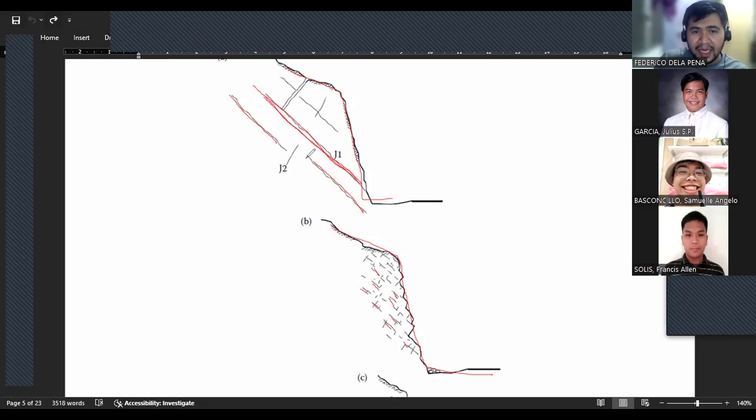Now, in terms of stability, that will have implications on how the rock slope may fail. If you have even just one discontinuity that is highly persistent, it can easily create an unstable block that can cause a large failure, like in this illustration. On the other hand, if you have low persistence joints, what they would normally form are small blocks, and they can fail as small blocks.